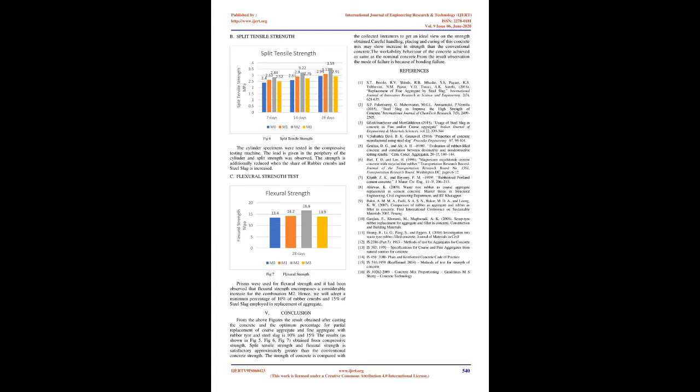3. Mix design. The mix composition is chosen to satisfy all performance criteria for the concrete in both the fresh and hardened states. Proportioning of concrete mixes may be thought to be a procedure set to proportion the foremost economical concrete mix for specified durability and grade for required site conditions. The fundamental principle of the concrete mix design is to pick the proportion of all the ingredients. The premise of the mix design is for 1 cubic meter of concrete, as shown within Table 6, with the partial replacement of fine aggregate and coarse aggregate by steel slag and rubber crumbs. The mix proportion of rubber crumbs and steel slag is as shown in Table 7. Table 6: Mix design.